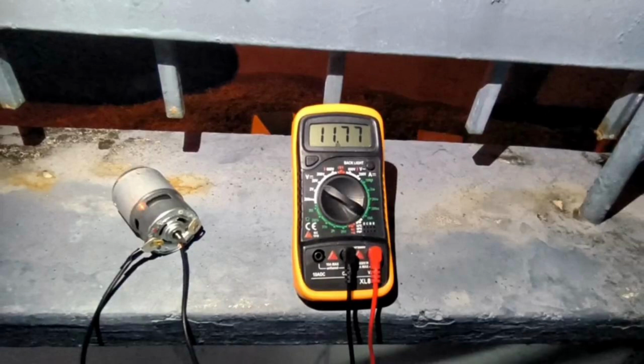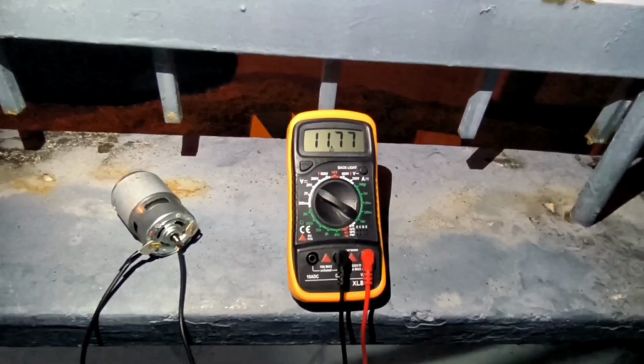Using the multimeter, we can see whether the alternator charges the battery or not when the shaft is rotating. The voltage increasing means that the battery is charging from the alternator. The load motor will indicate if the battery is charging or not. If the load turns on by itself when the alternator shaft is not rotating, that means the battery is discharging, and vice versa.